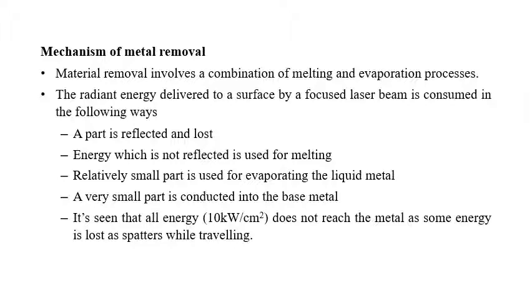When a high energy density laser beam is focused on a small work surface, the thermal energy is absorbed, which heats and transforms the work volume into a molten or vaporized state that can easily be removed by the flow of a high pressure assist gas jet, which accelerates the transformed material and ejects it from the machining zone. In this way, the material removal process takes place in laser beam machining.